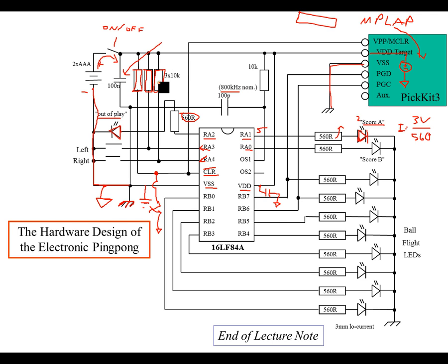If you didn't have the resistor there, when you push the switch, you would have, ideally, infinite current flowing through this, and it would completely deplete your battery. Your battery would be dead in a matter of seconds. So you have to have these resistors here. And again, you want these as large as possible to minimize the amount of current through them.